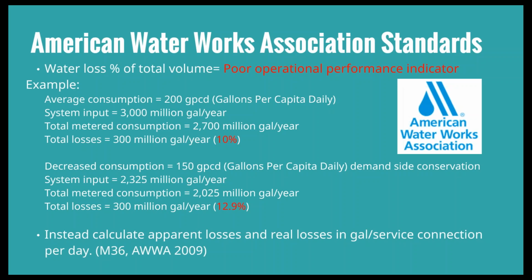I was just on a construction site today, and they're doing repair of a pipeline, but the closed valves are probably allowing somewhere between 50 and 100 gallons a minute of water loss right now. And I'm sure nobody's metering it. So there's a lot of those type things that go on in a system when they're doing maintenance that aren't really metered and aren't being accounted for when you're doing your audit.